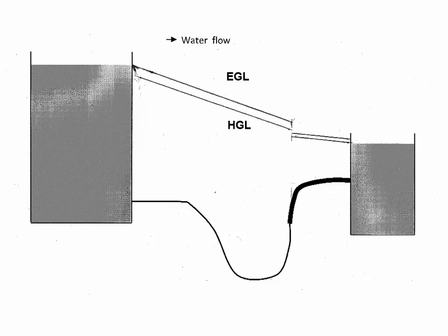Your drawing may look a little bit different from this, but there are some things that you have to have. So let's talk about what has to be present to be correct. This one has to be not as steep as the first pipe. The first pipe is steeper because the diameter is smaller, so you're losing energy more quickly through the small diameter pipe. So that's one thing: here you have steep, here you don't.